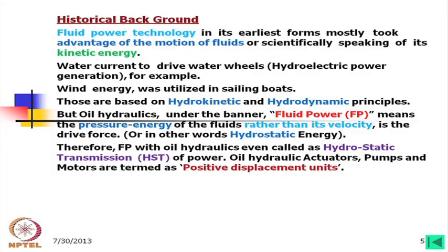If we think of the turbine, there the fluid with potential energy is converted into kinetic energy, and that transmits the power to the impeller of the turbine, and the turbine rotates. Whereas in the case of fluid power, we supply the pressurized oil inside the actuator and it moves, giving thrust to the piston, like a solid bar generating a thrust on it. Alternatively, if we use rotary elements, there also the same pressurized oil is working, and that is why it is called hydrostatic.